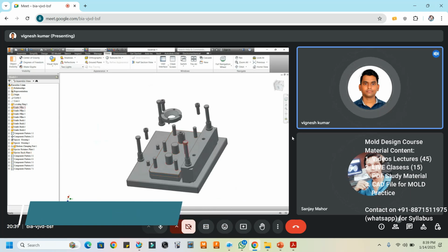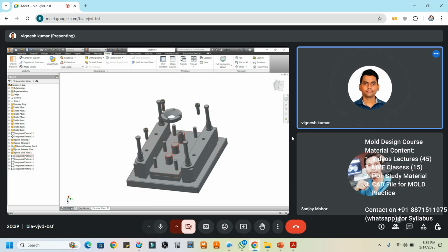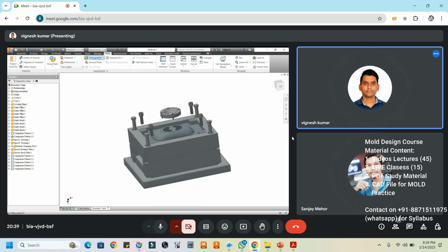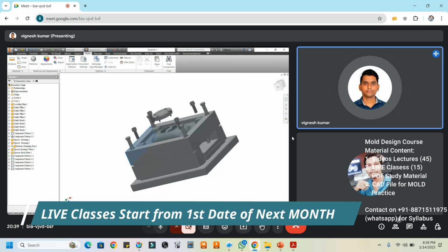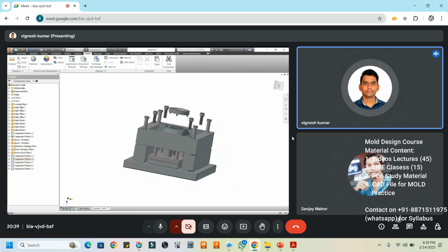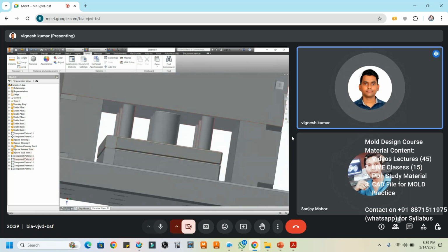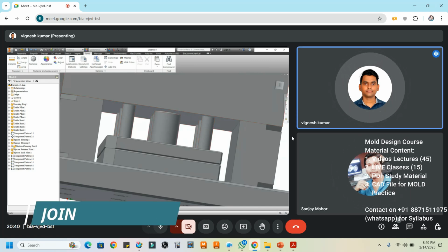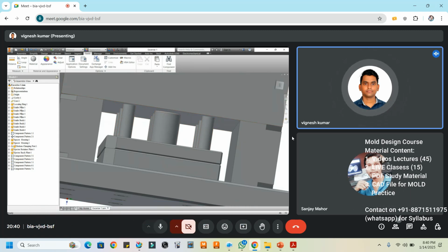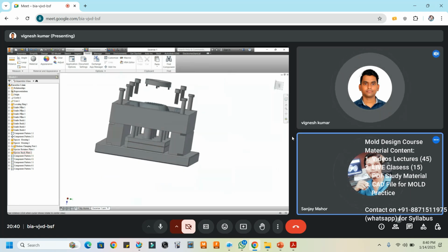First of all, I have done this for this work, right? So based on your design size, I have calculated all these things. Approximately this is 260 across, somewhere like 210. How do I calculate? I know I should put the return pin here as well as a spring here. How many return pins should I take, 4 or 6? Does it depend upon the part or weight of the mold, or can I use larger return pins with a smaller quantity, or smaller 12 dia, 16 dia return pins with more, 3 or 6? How do I evaluate that, sir?